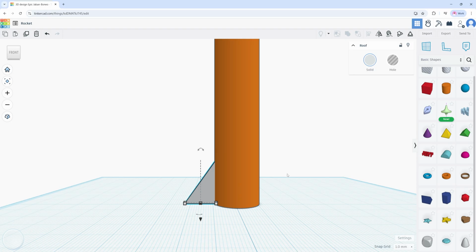And now I need to add it over here. So I need to create another fin. To do that, there is an easy option which is known as duplicate. So just press Ctrl D to duplicate it, and then we can rotate it and align it, or the easier way is to mirror it. So if I press this mirror option, now I have the other fin. I just need to select on which direction I need to place it. So I need to place it in this direction, select on this. So now you see you got the mirrored object.